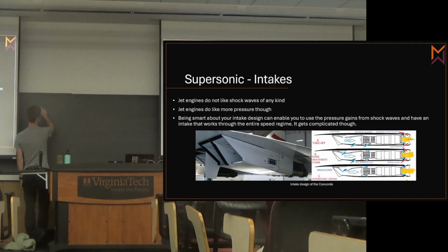So a really typical case is a ramp that's not angled, then two angles like this. So this guy makes a shock, and this guy will also make a shock because the flow is going this way, and now it's changed from here to here, so I can do that angle thing again and figure that out, and I'll have another shock.